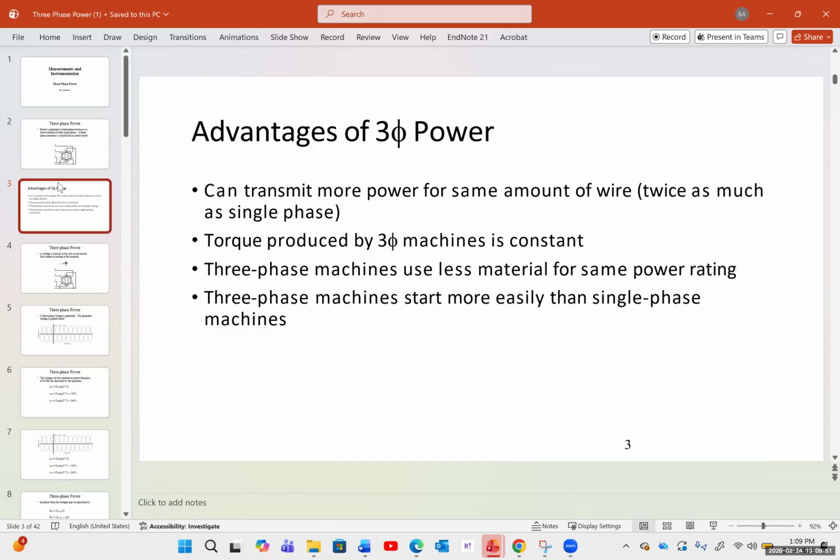Because when you have less material, the motor will be smaller. Less material means less copper. Copper is expensive, and you're going to end up with a smaller motor. And the other problem is you don't have any added benefits. When you go higher than 5 kilowatt, you need a very thick wire to bring that power. You need like a 40, 50 amp single phase, which most certainly you can't find in most places. So after 5 kilowatts, usually you jump to a three-phase.